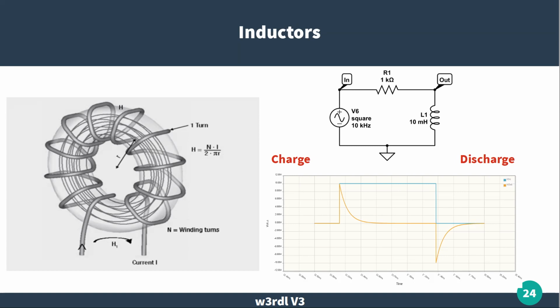And the one thing you notice, all those magnetic lines of force are inside that core. So there's essentially no magnetic lines of force outside of that, so it won't interact with another coil next to it. Whereas with your other coil, you have to be careful what it's next to, because it can have an effect from another coil or another component. That's why about all you see nowadays is toroid inductors.